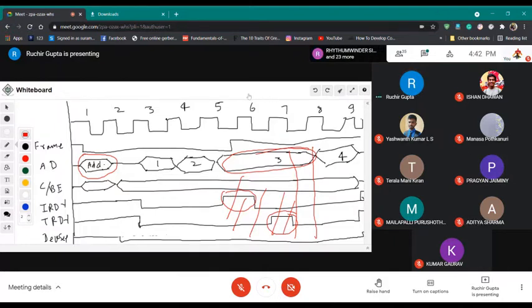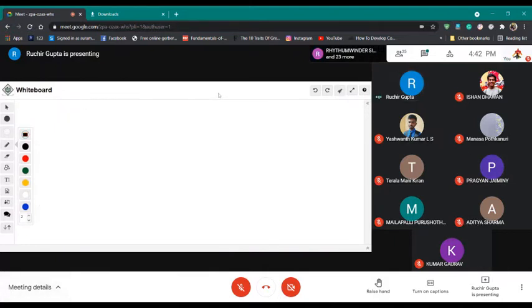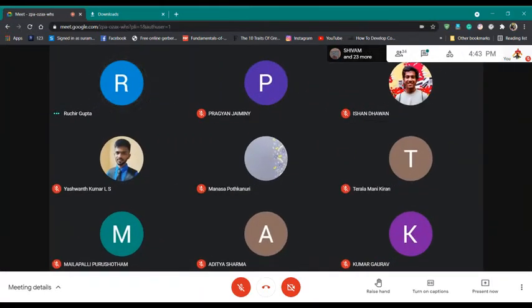I'll just delete this. So now we said that it is a plug and play thing, right? In plug and play, while you are connecting a device, you don't have an address for the device because so far no address has been assigned to that. So how to handle that situation? For that, this configuration address space is used. We'll just talk about that configuration address space.